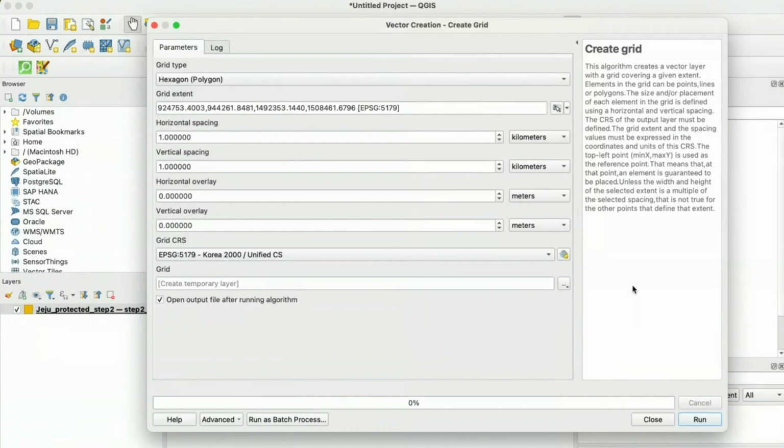That's why when we do GIS for a country, usually we choose EPSG system because it has a kilometer or meter unit, which is much more useful for a country. But for a country like Russia, Australia, or maybe United States, using EPSG wouldn't be the best solution because the entire land area is pretty big. So in that case, maybe WGS system can be much better.